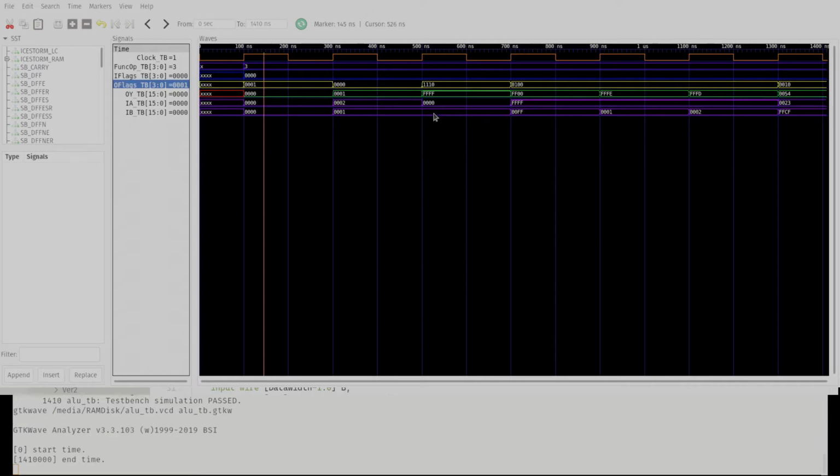In this case, we're subtracting 1 from 0, which leads to a minus 1, and minus 1 is all F's. And in that case, we don't have a 0. We have a carry flag set, which in this case is called the borrow flag. It also yielded a negative number, or the most significant bit was set, and it also caused an overflow. On the next case, we're subtracting FF from FF on the lower side, and we get FF00. That's what we expect. We also expect that it's not 0, no carries or overflows, but it did set the negative flag because the uppermost bit is set.